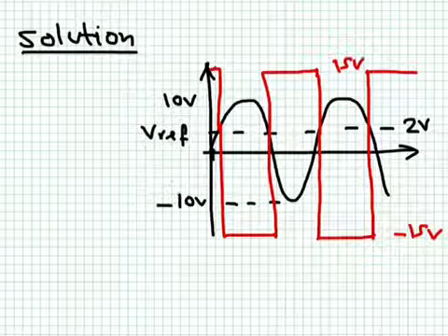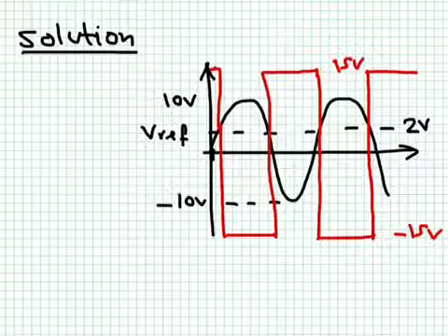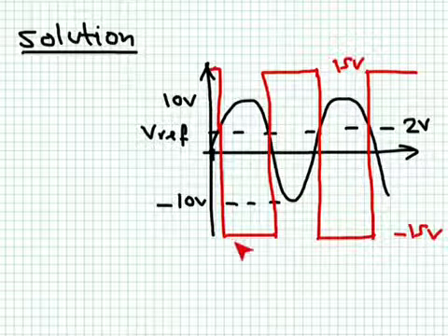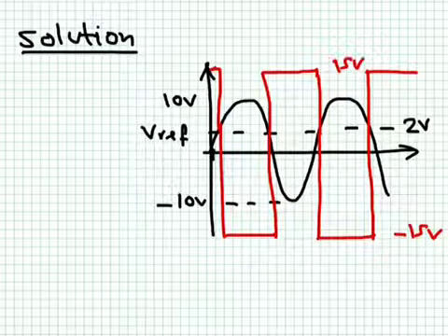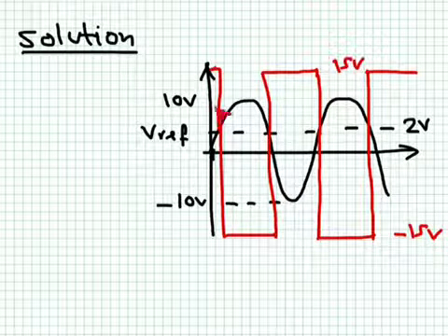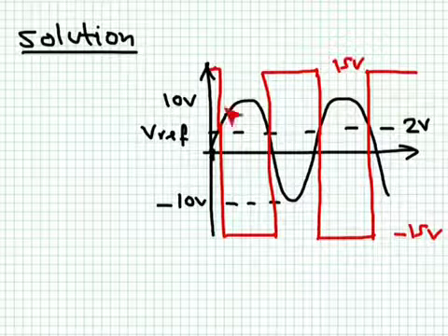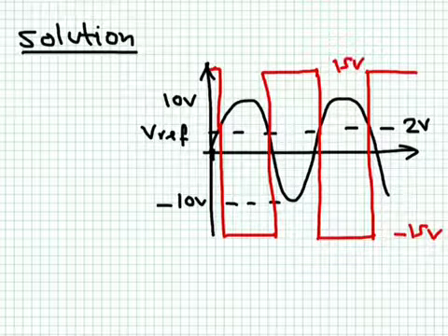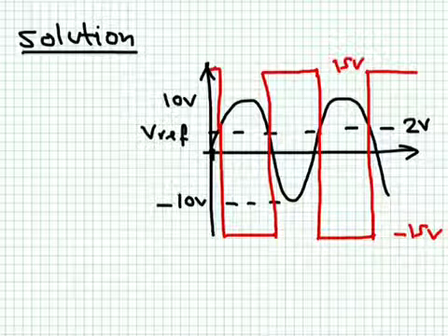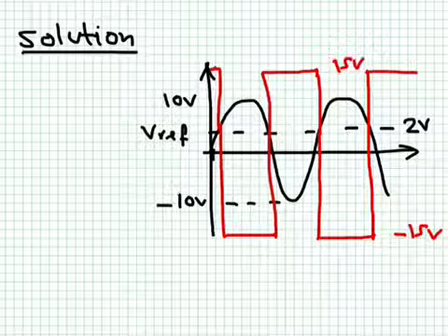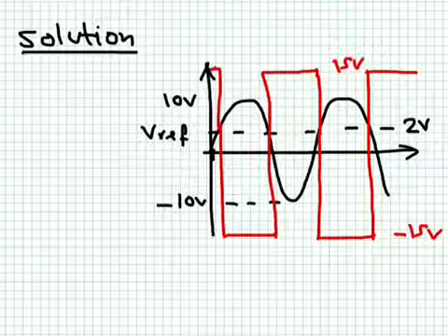So if you try to plot V out and Vn, this is V out here, the red line, and this is Vn. Notice there is 180 degrees phase shift between them. When this is maximum positive, this one is maximum negative. And the reason for that is because I'm applying my input to the negative terminal. It's a little bit different from the theory we explained earlier.